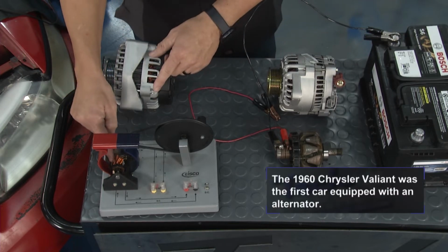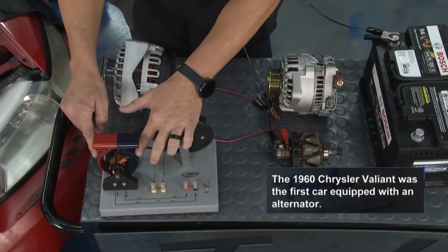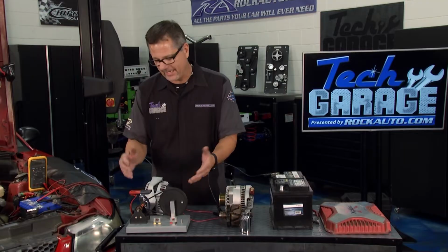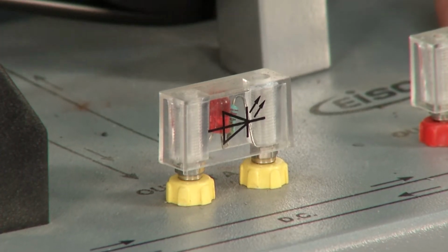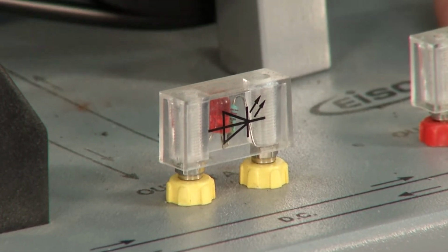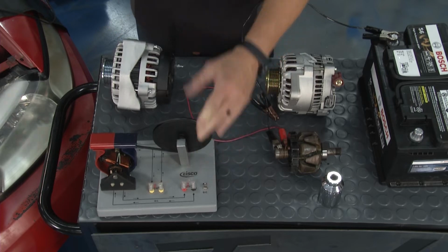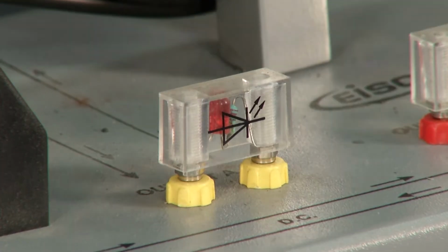This is the actual rotor assembly right here, and here's the stator. And it induces a voltage, and it makes voltage. That's pretty cool. I can do it right here. We spin it around. I have no electronic source plugged into this whatsoever, and bam, I'm making an AC output. Eventually, it rectifies it, gets it back to the battery as DC.